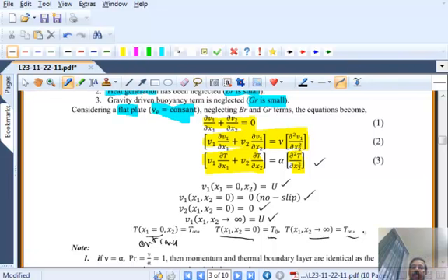The question that I guess I would like to ask at this time is to probe the question that you raised. Okay. Before that, let me ask you, what is the nature of coupling? Does fluid mechanics affect heat transfer? Does heat transfer affect fluid mechanics? Do you need to solve all the equations simultaneously, or can you solve for some equations first and then the other equations next? Do you understand the idea of coupling, right, between equations?